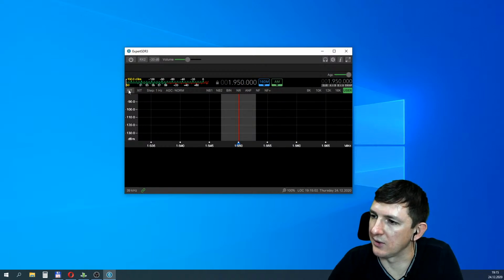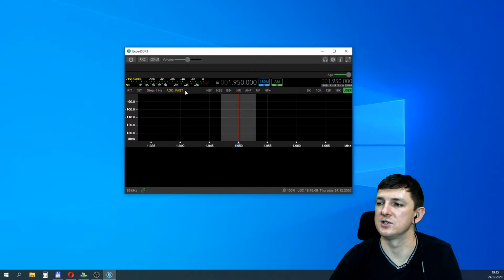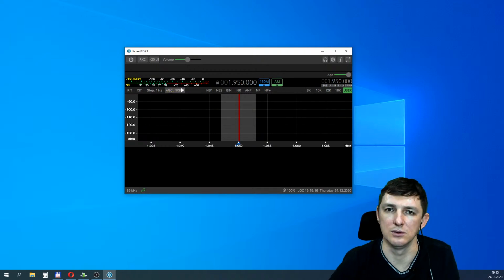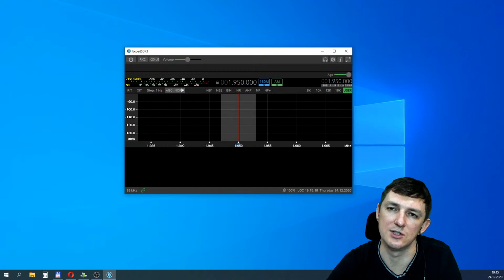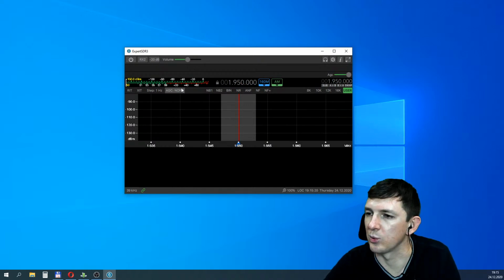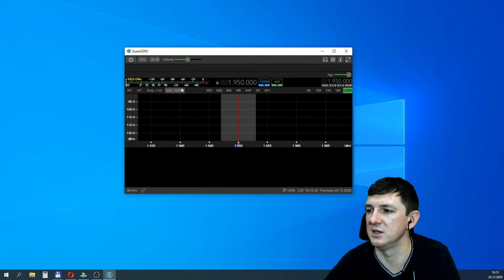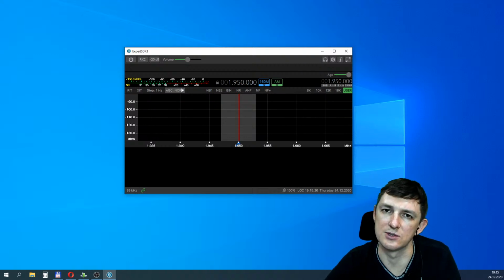Okay, the step button. AGC in Expert now has just 2 positions, fast for CW mode and normal for other modes, because all voice operations and digital modes require just long or maybe slow AGC, and 2 positions is enough.